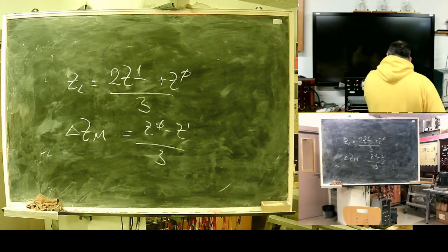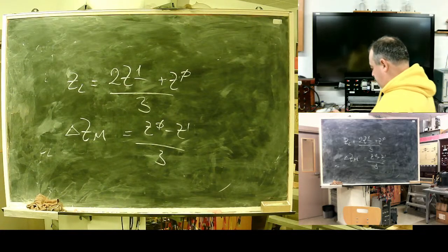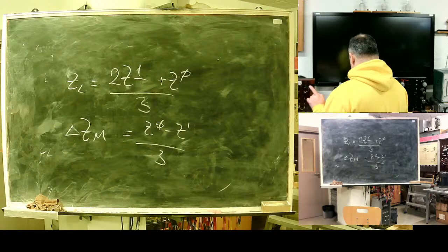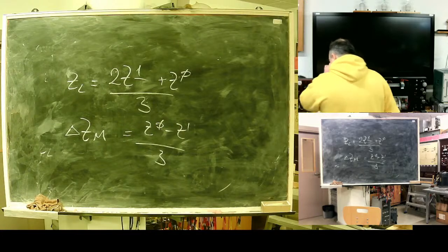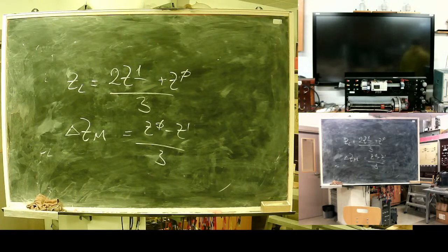I need to repeat it. I wrote these formulas assuming a full transposition cycle. If you deal with a line without a full transposition cycle, go back to Carson's model, go back to the point where I assumed 3 elements, and calculate precise elements assuming your line is 1 segment, not 3.